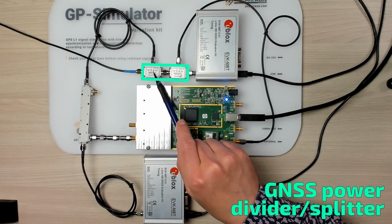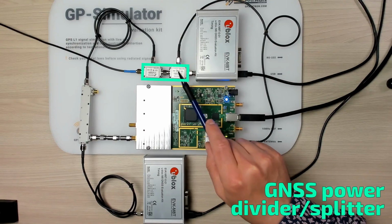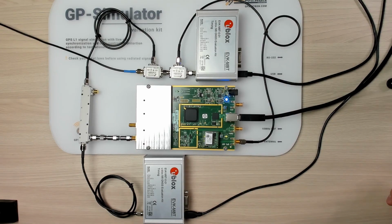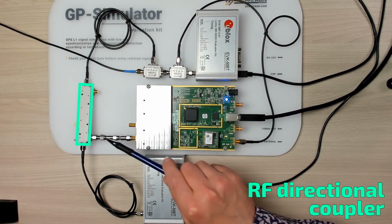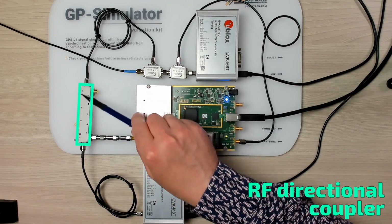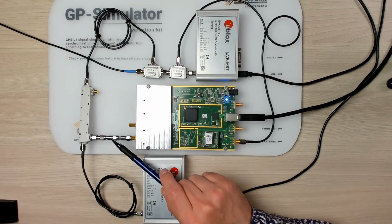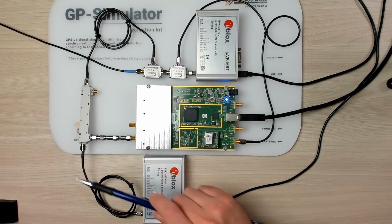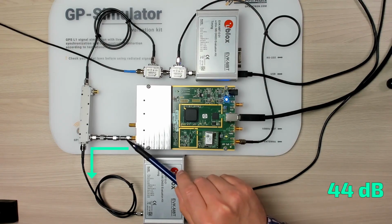Then we see two power dividers. They're used to share one GNSS antenna between three receivers: 1, 2, 3. This is a directional coupler to mix the spoofer signal with the original signals. And in addition, we use two 10 dB attenuators to reduce the output power of the spoofer. In total, we have about 44 dB of signal attenuation along this path.